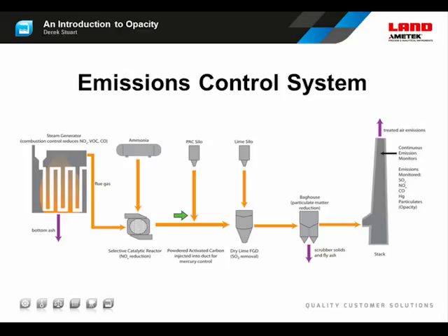Second phase is mercury removal, which is being implemented throughout the United States at the moment, and generally uses powdered activated carbon, which scrubs metallic mercury and ionized mercury from the flue gases. And mercury is a heavy metal and a cumulative poison, and a very large source of mercury in our waterways and in our food is actually the mercury from coal, which previously went up the stack and out into the environment.